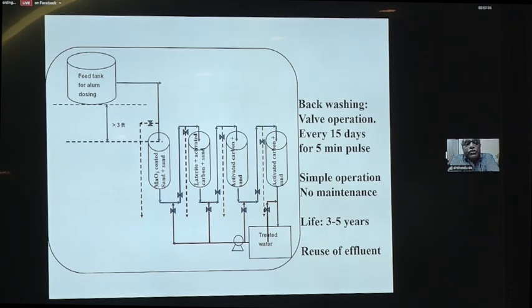Then it is passed through a laterite bed and an activated carbon bed, where any organic material, any odorizing agent, any leftover organic material will be disintegrated and degenerated, and then it passes through two carbon beds, and the water is polished, and we get the treated water.